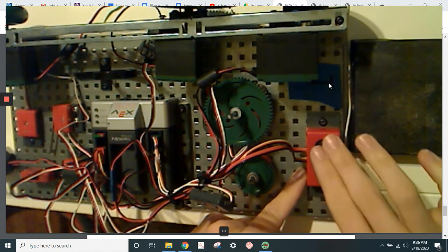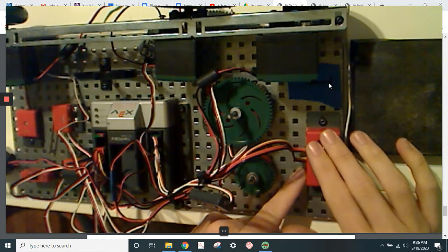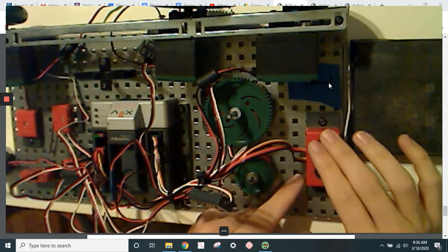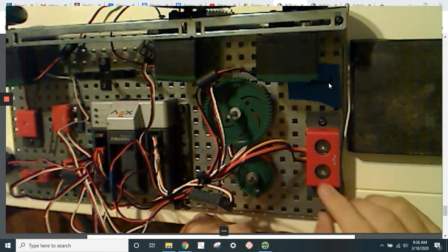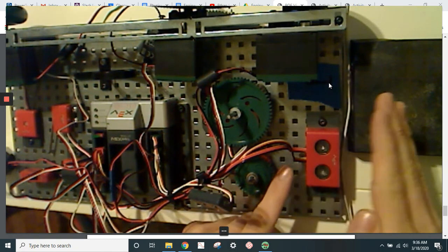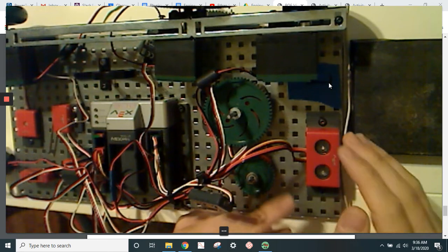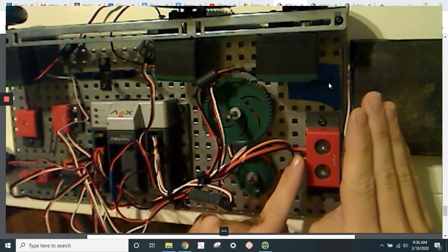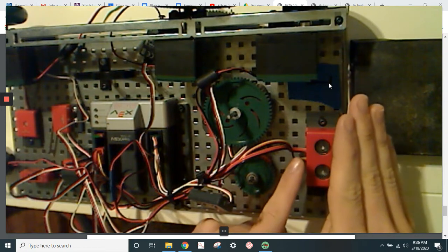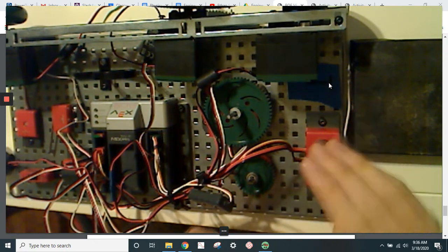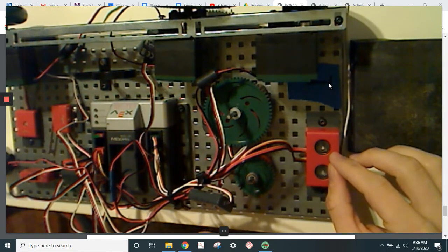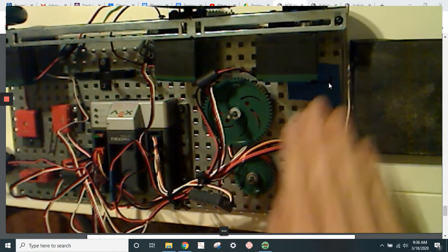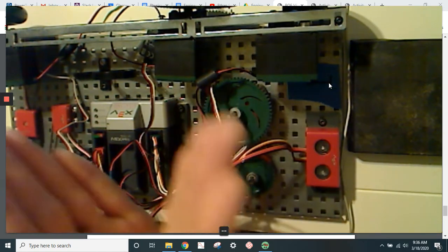It sends out a sound wave that's inaudible to us, and it travels. Let's say that there's an object above it. It bounces off this object and comes back down into this other side, and it picks it up. Because the speed of sound is relatively constant in air, with slight fluctuations based on temperature and density, it can calculate how far away something is. I believe that this can see things up to 250 inches away, if I'm not mistaken. It can sense those, but it has this kind of cone that it sends out.